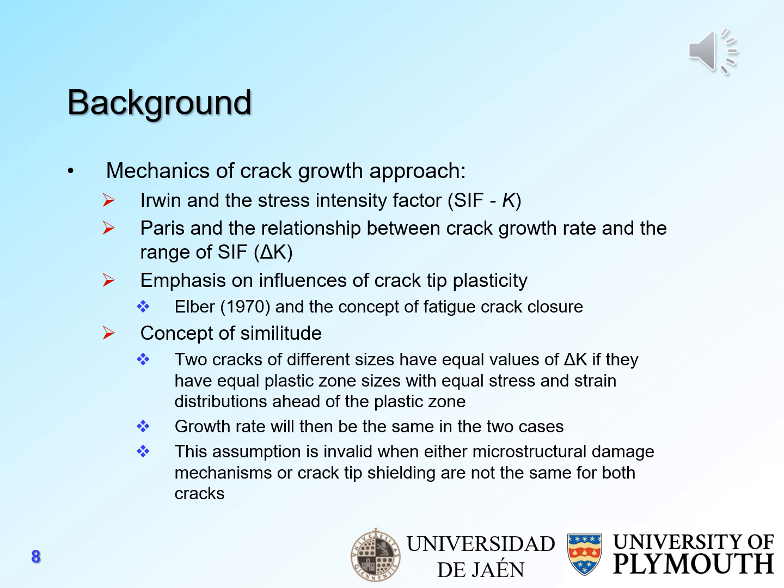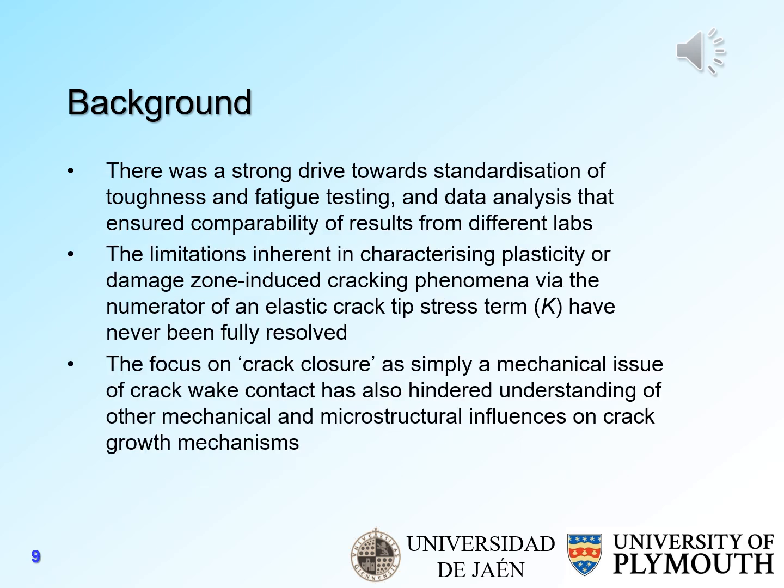In the mechanical engineering community, there's also a strong drive towards standardization of toughness and fatigue testing and of data analysis, because it was necessary to ensure compatibility of results from different laboratories. The limitations inherent in characterizing plasticity or a damage zone-induced cracking phenomenon via the numerator of an elastic crack tip stress term, i.e. stress intensity factor, have never been fully resolved.